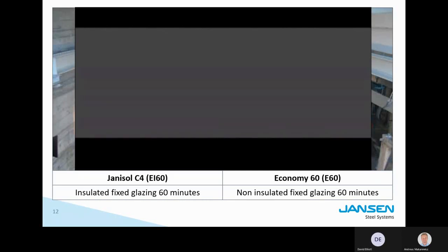You know, for each building, you will have a fire plan, so to speak. The fire compartments, the division of the building, and the barriers between the compartments have to be chosen right. So you have to know where you have combustible materials. There you probably should not use this type of protection. You should use EI. Where you don't have it, for example, concrete corridors, which just are there to lead people out of their offices quickly and without any delay. There you can use E class, no problem.